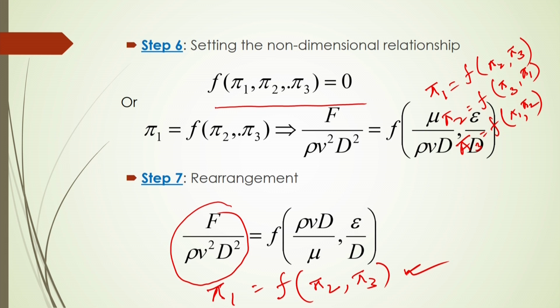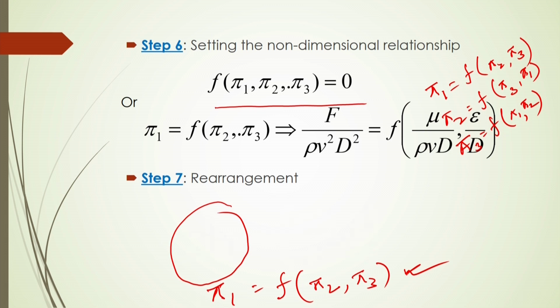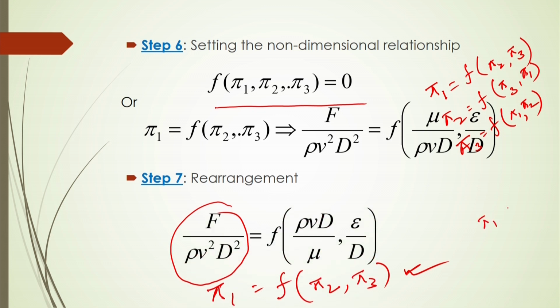Now, an important point is that after making the dimensionless groups and functionality, what do you have to do? You can make an exact relationship among these groups. How? You just say phi 1 will be equal to some coefficient lambda times phi 2 to the power a and phi 3 to the power b. So, this is your exact relationship.